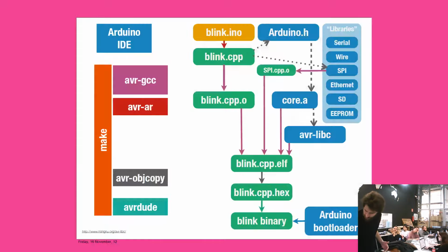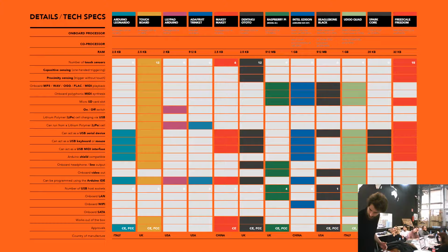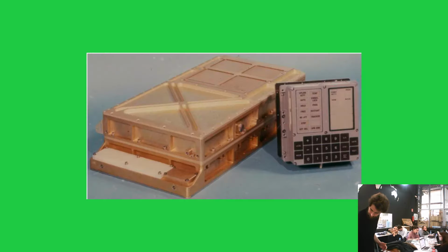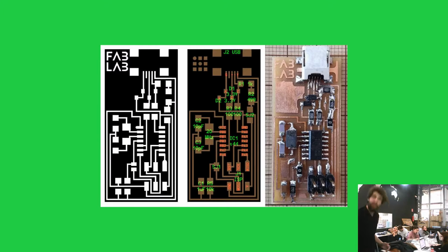Just before we finish, and I don't want to annoy you more, just to finish clarifying a few things about what we're going to build. So that's a FabISP, okay, and it has these connectors here, right? The same as the ones we looked at on the Arduino. And it has a USB connector, and we'll use a chip called an ATtiny44, which is a microcontroller that you can program, right?